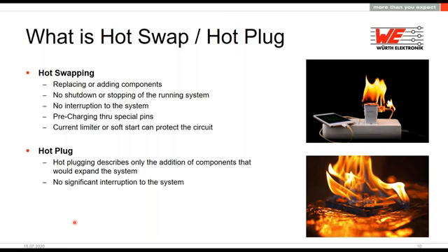This is to make it clear that you use this hot swap and also hot plug, so that there is no failure in your system and you don't have to shut down your system. And also, when you plug in an application with a high energy density, there is no spark and so on. This is why this IC makes this spike at the beginning to check, okay, is everything there?